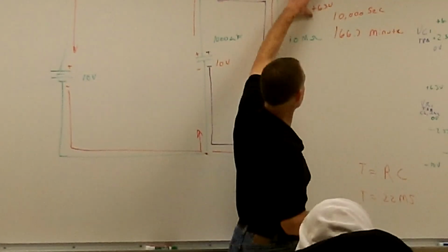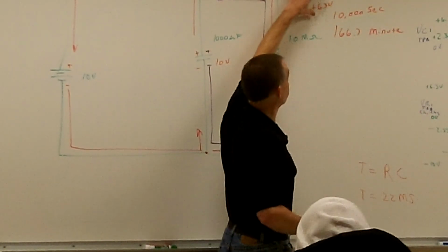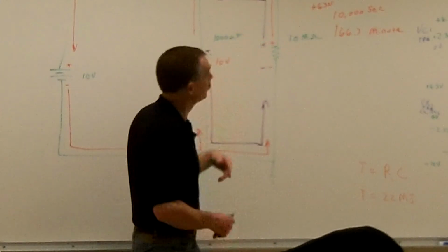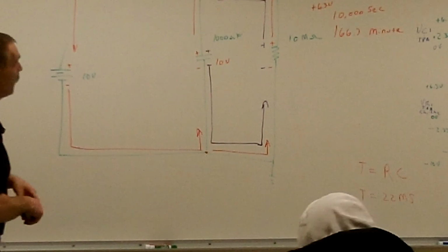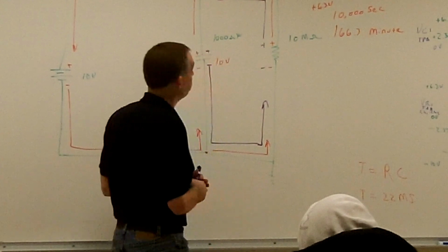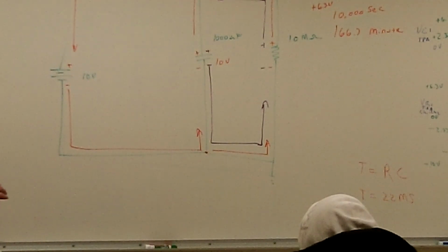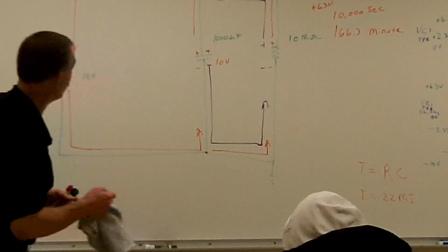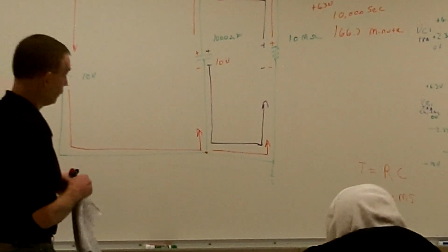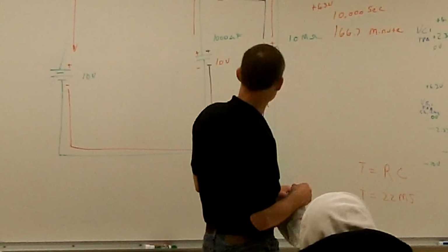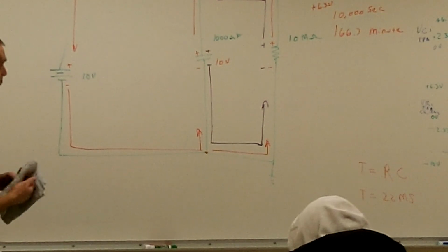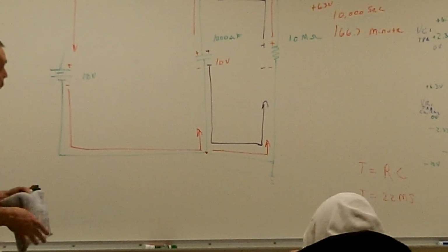And depending on what that range is, I could even say that my acceptable output range could be 10 volts to 3.7 volts. Depending on what I want for range, I could go multiples of different time constants for that. So those are some of the applications that we use for RC time constants. We can make on delays, off delays, depending on if it's in series or in parallel, and we can come up with different circuits, and that's all our timing circuits.